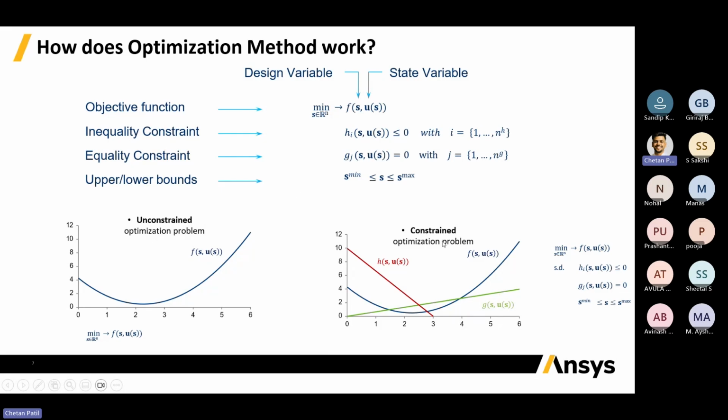So over here you can see how the constraint optimization works. Basically, you can define different kinds of constraints over here to achieve your optimization result. Whatever constraints you have applied, consider you are applying a displacement on the geometry as a constraint. So your body can undergo only some amount of deformation over here.